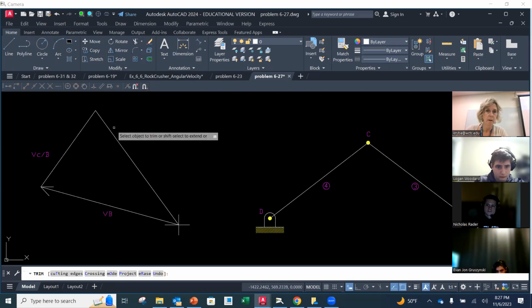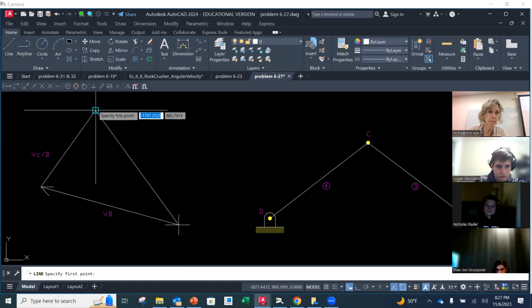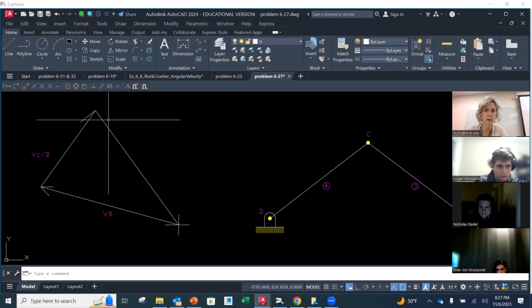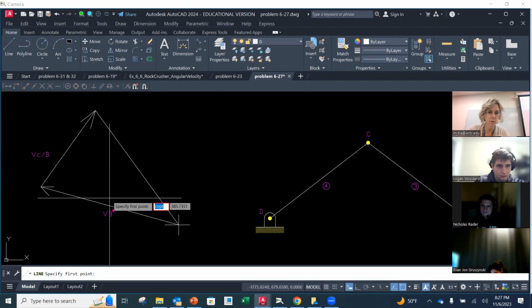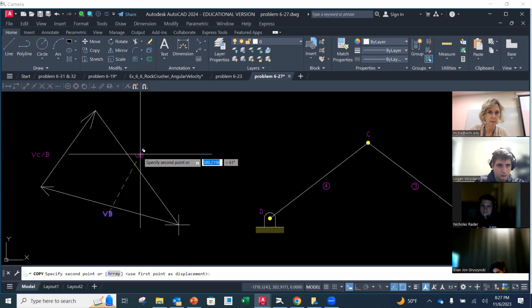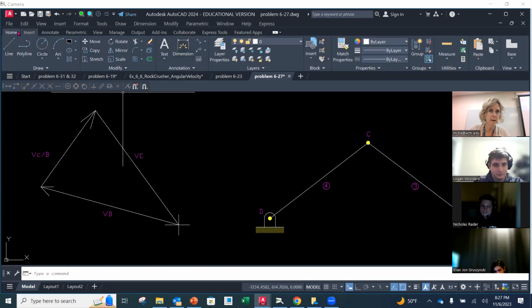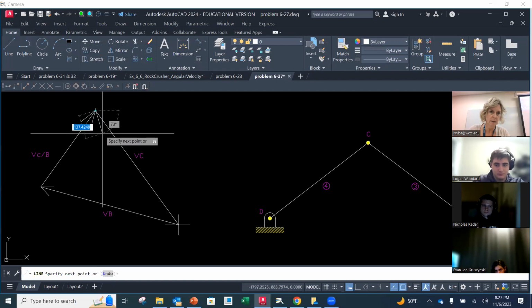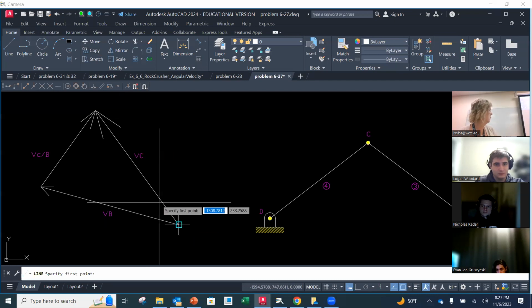Okay. Now, arrowheads. So if this is V B plus, vectorially, V C relative to B, my arrowhead is going to go there and there for C relative to B. And then I need to copy this one and change this to the velocity of C. And its arrowhead is going to be at the endpoint of the other side of the equation, right here.